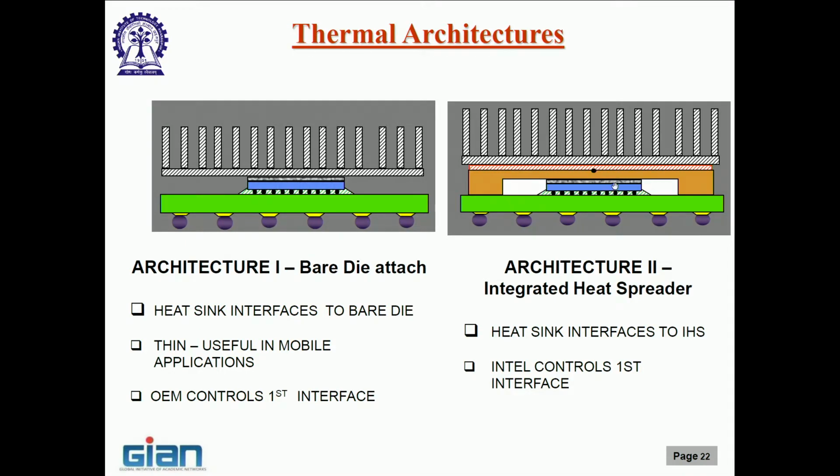All right. Many a times for this type of package, this is called TIM 1 and this is called TIM 2, thermal interface material 1, thermal interface material 2. For this one, do you call it TIM 1 or TIM 2? I think both are used pretty often, and both are okay. TIM 2 if you look at it from the heat sink side, TIM 1 if you look at it from this side, because there is only one level of interface here. Okay.